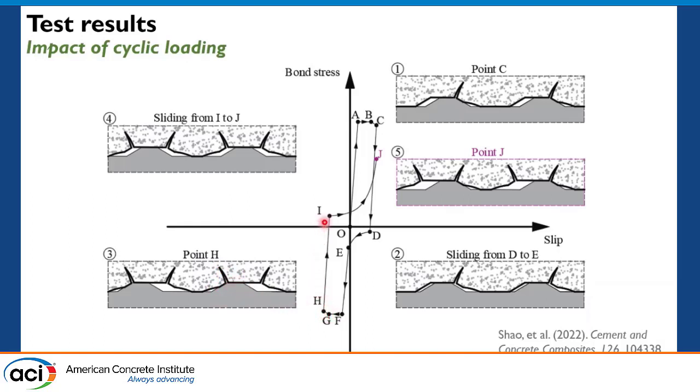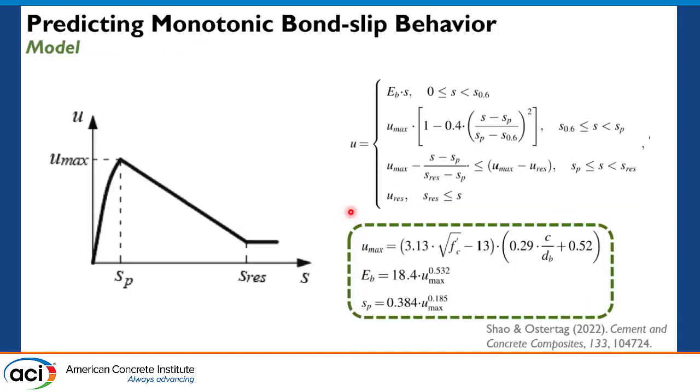And then if we want to reverse back to the original direction, when the steel rib gets in contact with the UHPC key again, the reverse cycle has caused more damage to the opposite side, so the remaining UHPC key was smaller than before the cycle was reversed, and that explains why we see bond strength degradation due to the reverse cycle. That's because the UHPC key was accumulating damage due to the reverse cycles. So that's about all of our experimental results, and then we will move to our prediction model.